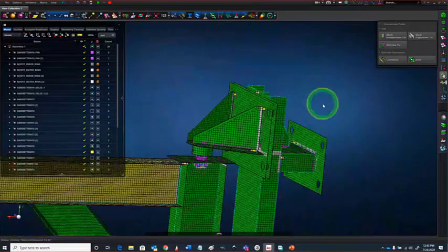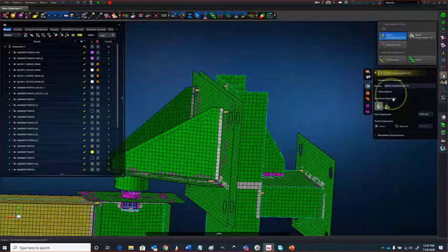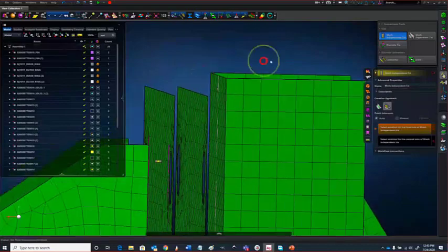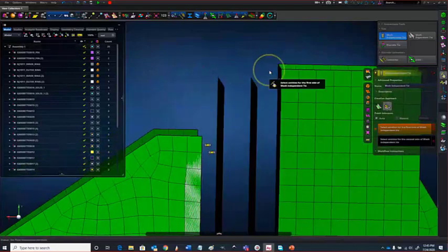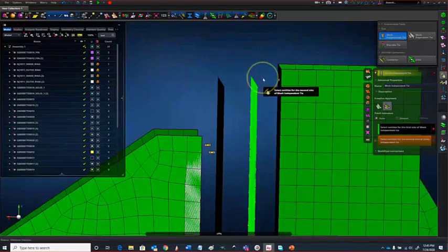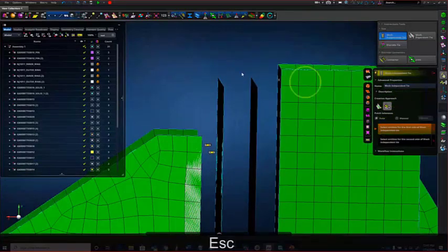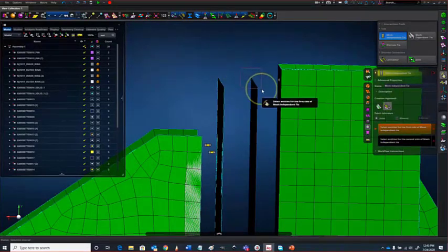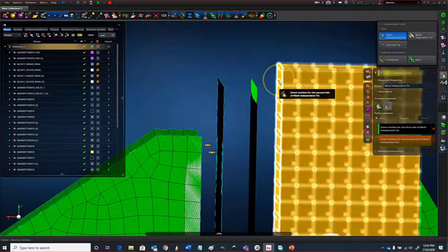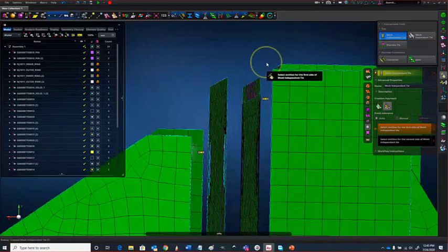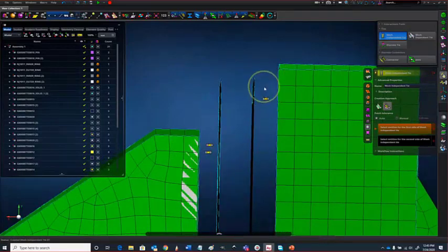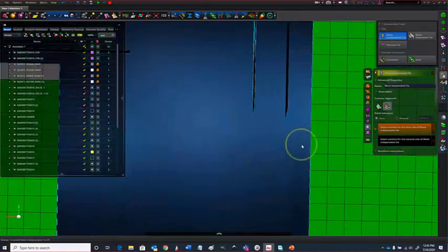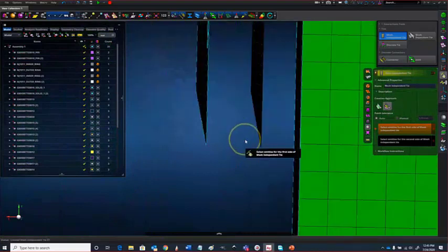And now I'll use a glue, but in a little bit more manual way, to show how to only select an edge of elements, which I haven't done correctly. Let's just repeat that. Switch to element selection mode. Okay, I'm only going to use those elements and that body. So now I have glue defined at the top elements to represent a weld. And I'm going to quickly do the same over here.